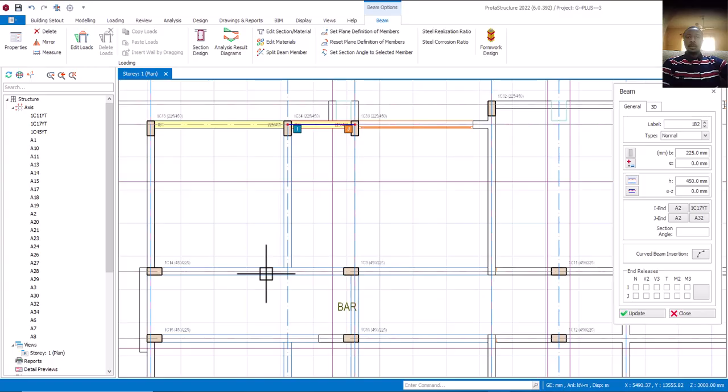So I'll come here now, click on this, right click, and pick my axis, offset, F2, 1388, enter. This one is going to be a ghost axis. Yes, I can make it a ghost axis. Is that okay? I don't want too many columns. Let me just leave it. Is that okay? Then take this property now.